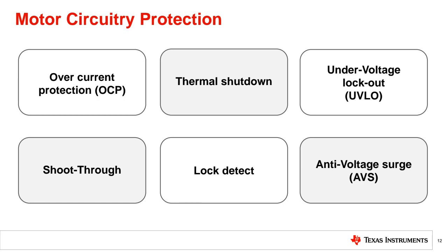Also another one, undervoltage lockout. You must use voltage detection circuits. If your input voltage goes below the rated voltage, your circuit detects that we are in the under-rated voltage region, and it will stop your motor. This is another protection.